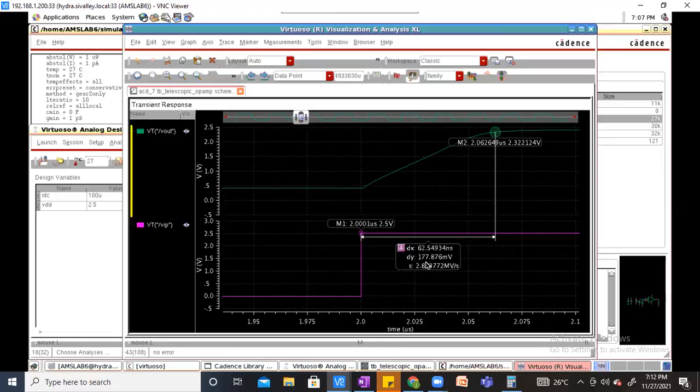It's 192 or 195 nanoseconds for the two-stage settling time, right? Here the settling time also got reduced because it is a high gain amplifier. Along with that, it is a one dominating pole system, because of which I'm getting very good phase margin.